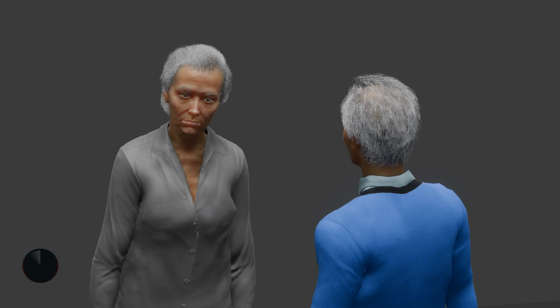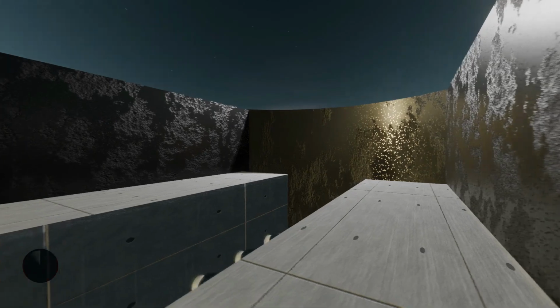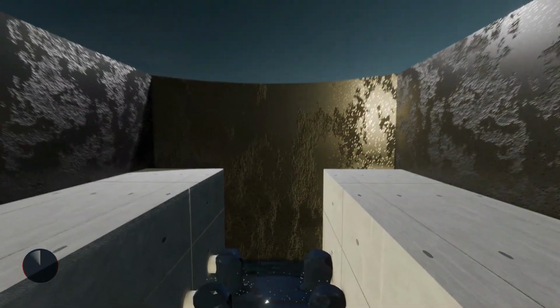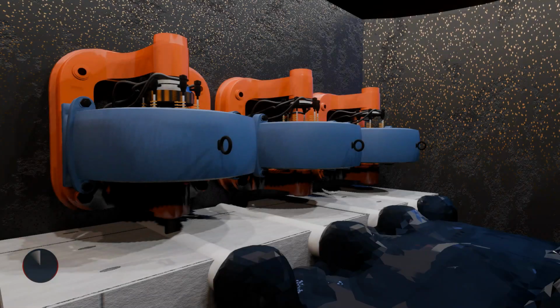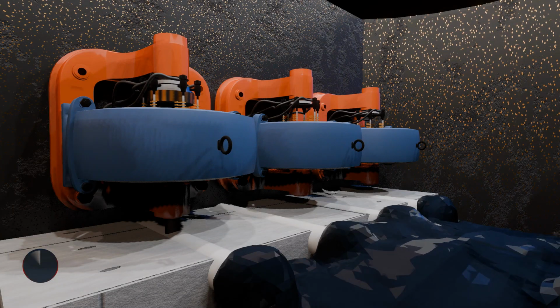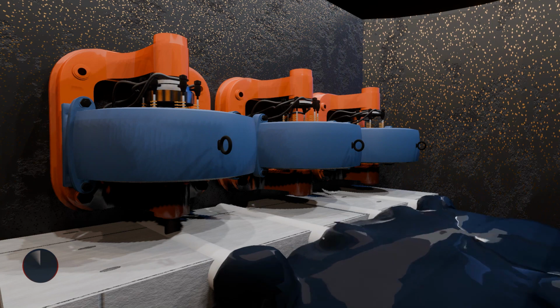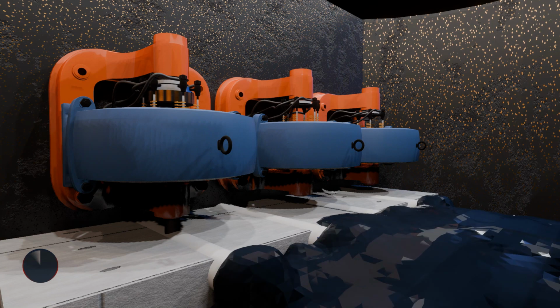Now that we have understood how fluid flow works in relation to the turbine design, we can now look at the working flow of hydropower plants. After the moving water has been dammed, water from the reservoir flows from the intake through the gate to the penstock and then spins the blades in a turbine, which in turn spins a generator via the runner, and electricity will be produced in commercial quantity afterward.